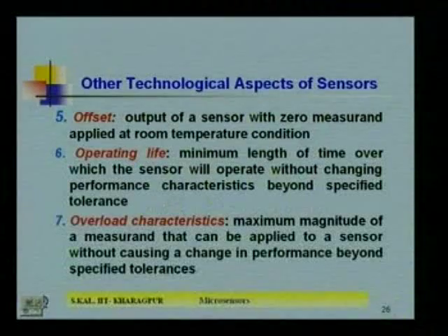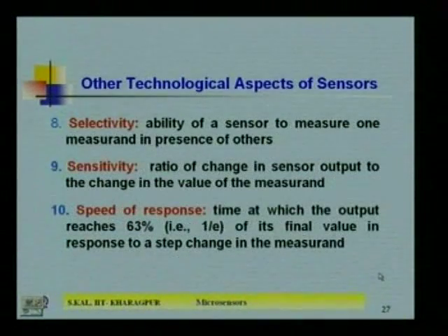It may show the exact value of the 200 dB or it may not. Okay, then that is not reliable. That means it has exceeded your specified tolerance limit, so it behaves erratically. So that's why overload characteristics are to be known for a particular sensor, so that you can use it reliably up to that level. Okay, that is the overload characteristics.